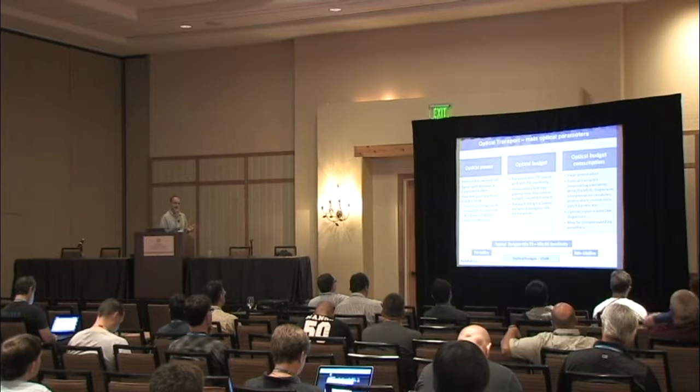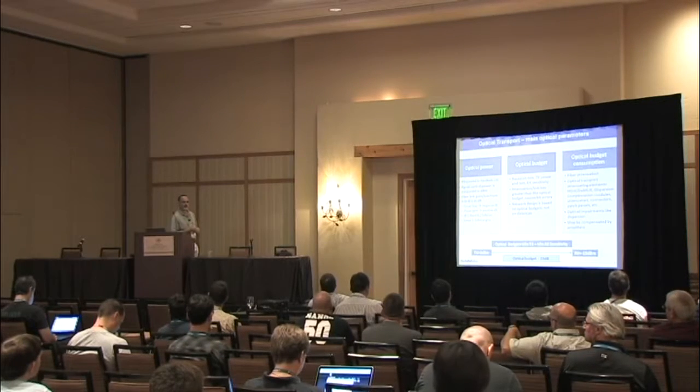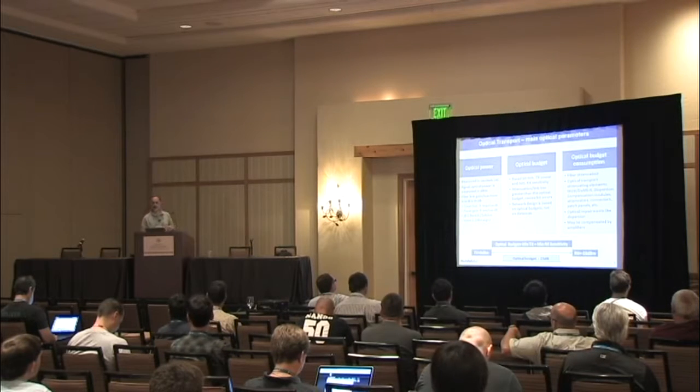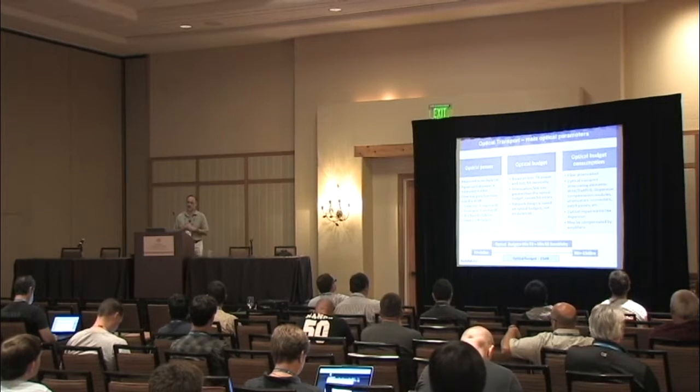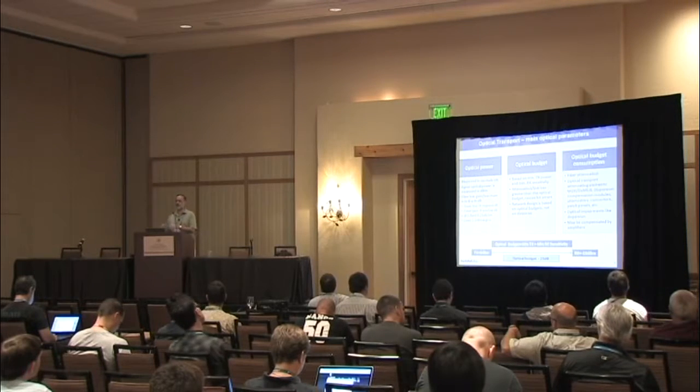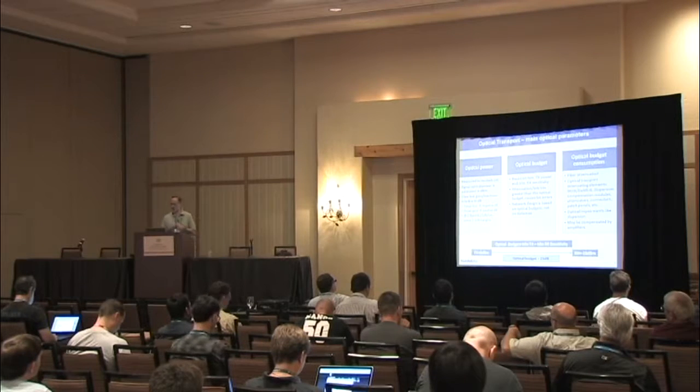Anything that generates attenuation. The main culprit is the fiber loss. You have 10 kilometers of fiber, which is going to generate fiber attenuation. And then you have all the other elements that can be simple attenuators or mux-demuxes or dispersion compensation modules, connectors, splices. Everything that is on the way is going to generate attenuation, is going to consume your optical budget.